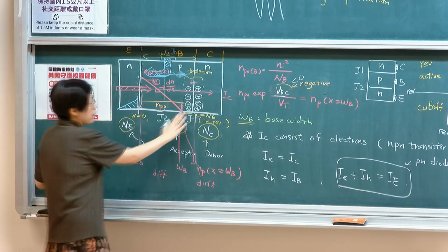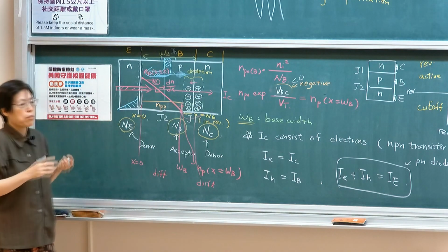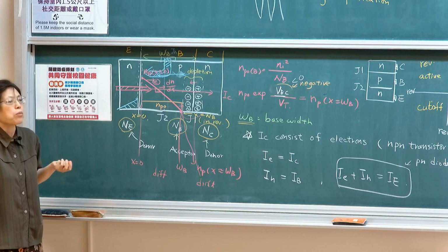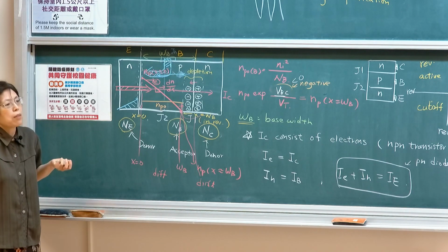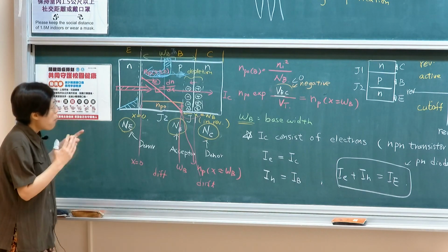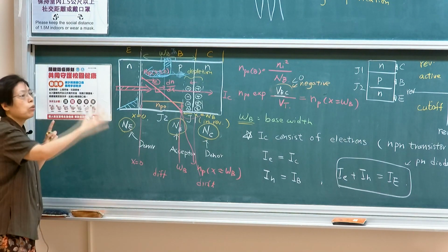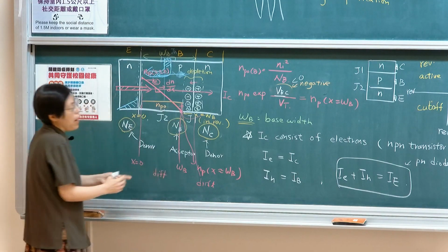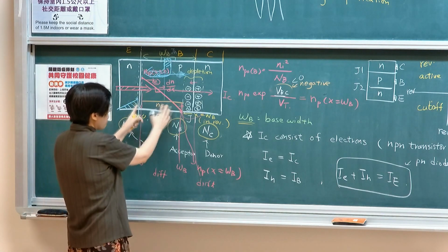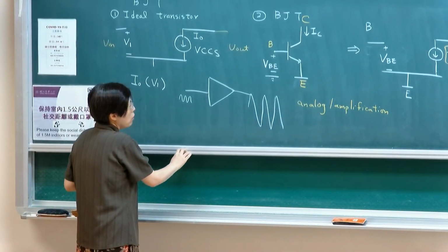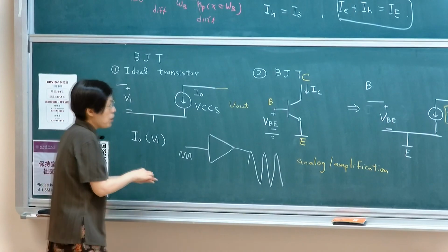But this is not a limiting factor, because the collector, like a vacuum pump, will take whatever comes in. You just feed it in and it does not limit your current. The part that limits or controls the total loop of electron current through the collector will be the diffusion current. So we're going to talk about how this diffusion current is controlled by your forward-bias p-n junction.